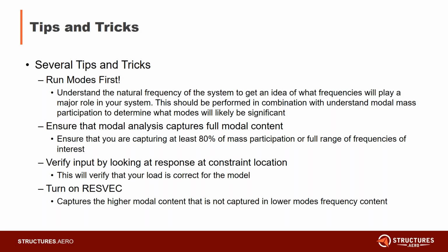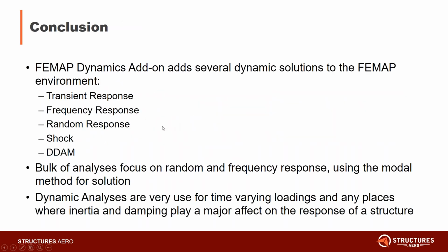Finally, turn on residual vectors. This will just make sure to capture your modal content of the system. So in conclusion, we've shown here some of the capabilities of Femap and how to go about setting up a frequency response and random response of the model, and just some tips and tricks on how to actually use this data. Some of the other add-ons that we didn't discuss today were the transient response, shock, and also the DDAM analysis. The bulk of the analysis that at least I've run in my experience in the aerospace industry is focused primarily on random and frequency response.